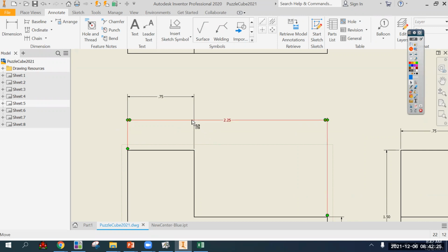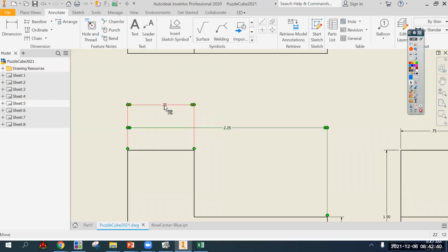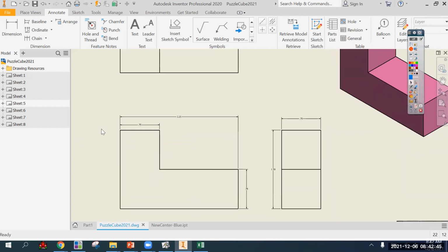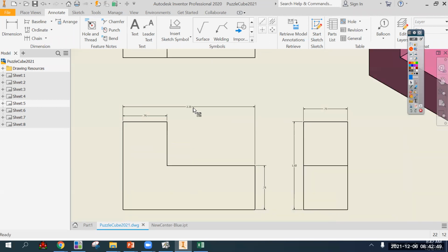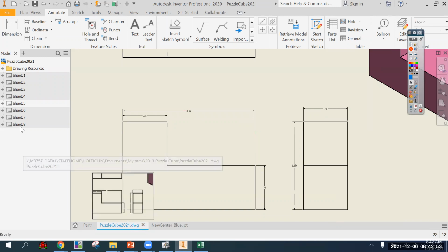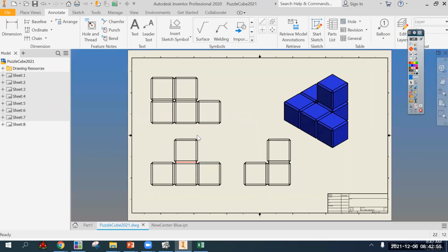And, you know, not just because extension lines are crossing, just think about what it would look like if you had a dozen width dimensions on there and some of the shorter ones were outside of the longer ones. It just doesn't make sense. And again, neat and tidy is part of it. Avoiding confusion, miscommunication, that sort of thing. And okay, so I'll do one on here.